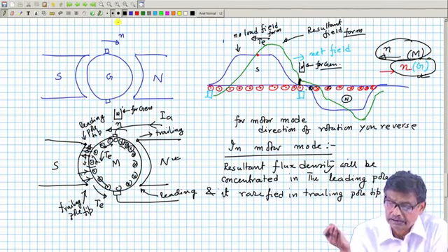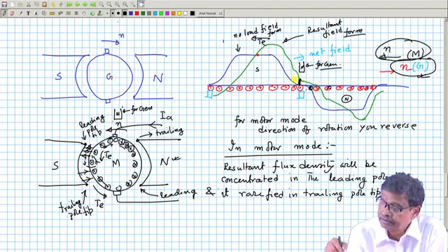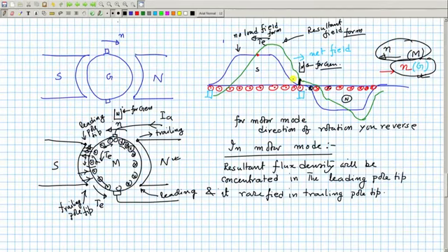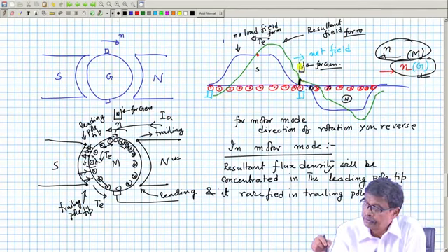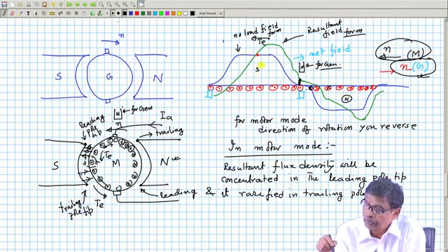There I also told that a coil which is undergoing commutation will get affected by the quadrature axis flux, and therefore, for a generator I can put some interpoles, thin poles, on the quadrature axis, that is where the brushes are placed. Current changes from dot to cross. The polarity of the pole should be the same as the main pole ahead, because south pole is positive. So, here some positive flux you have to nullify, and sometimes the strength of this pole is made slightly higher.